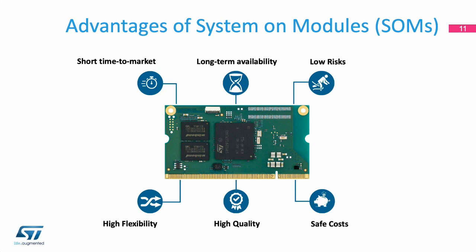But then there's another aspect which is speaking for the usage of SOMs, which is increasing the design success. What do we mean with this? Well, the computing part can be quite complicated, and therefore there are many parts where an error might be happening during the development process. And in order to avoid this issue, you can just rely on an approved system by again using a SOM. And finally, our DHCOM SOMs are sharing a family design, which means that they are interchangeable. So maybe you've designed your hardware and in a few years you realize that maybe you want to add some software features, but then you also realize that your SOM is maybe not powerful enough anymore. And in that case, you can just pick a new DHCOM module, populate your existing baseboard with a more powerful DHCOM module, and therefore you can increase the capabilities of your product without the need of a huge redesign.